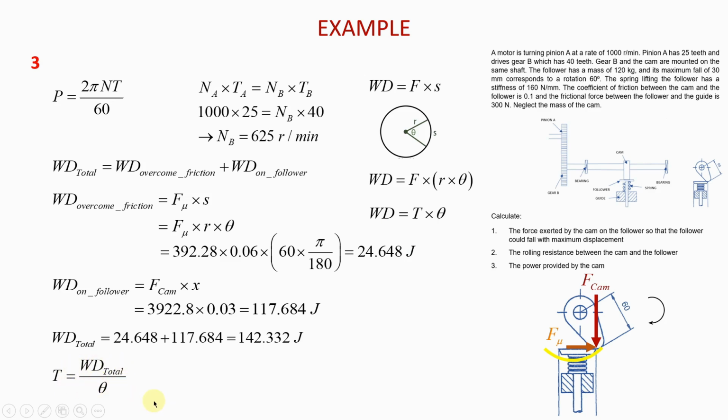And so if you plug in the numbers, this is what you will have. And notice here that I again changed the angular displacement to radians. Okay, always do that. And then the total work done was found earlier, and this is the number, so we just plug that in here, and then you will get the torque, which is this here, 135.917 Newton meters.